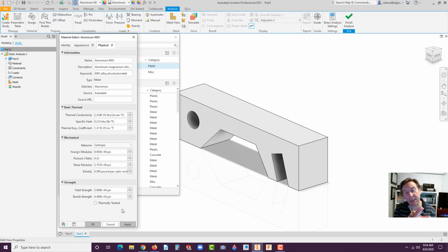So if you pull on something, let's say this is a metal, and I pull back and it bounces back, you've not met yield yet. And whatever the yield might be, in this case it's 3.989 for the yield strength in PSI. Once it gets past that or hits that, if you bend it, it doesn't bend back. It stays permanently bent. And so, again, that's why they call it failure. It doesn't mean it broke, but it did bend. And just be aware when things bend, many of you in engineering know this already, it can get strain hardened, especially if it's a metal. In strain hardening, you'll find it's difficult to bend it back, and then you've just created a whole other issue.